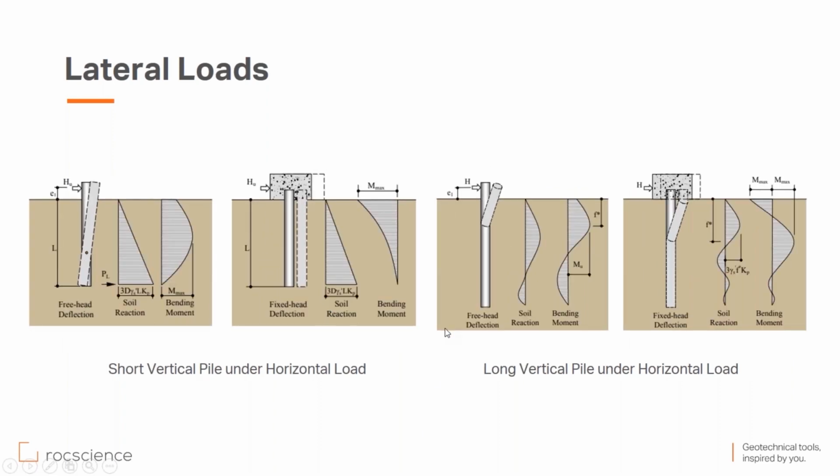What we need to see from our pile analysis are usually bending moment diagrams along the depth, soil pressure along the depth, skin friction, end bearing, resistances of the pile, shear force distribution along the pile.